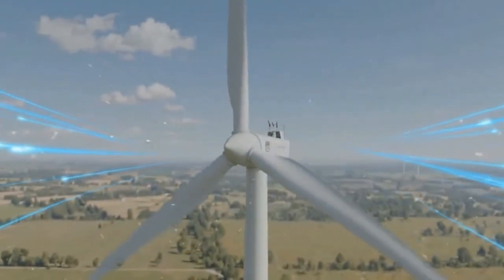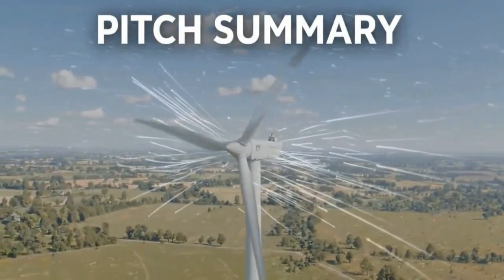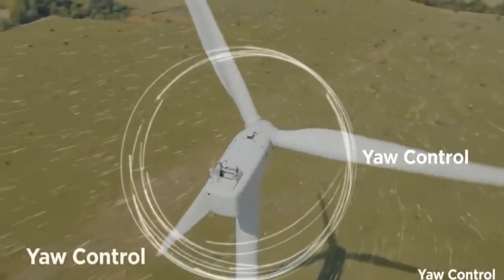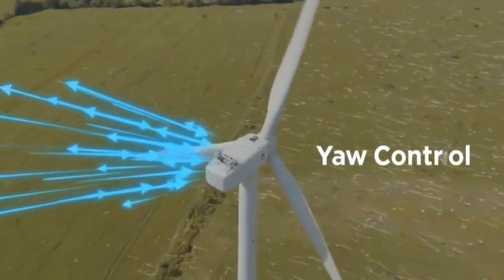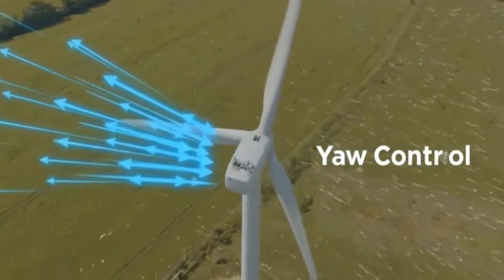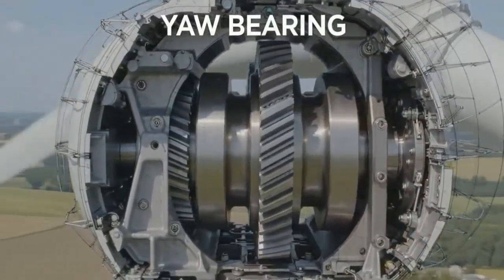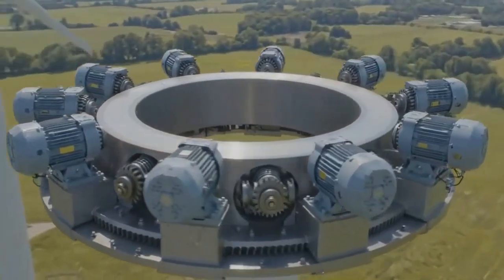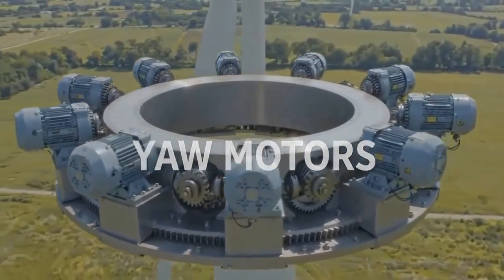In normal wind, the blade angle is set to create useful lift and keep the rotor turning efficiently. When wind becomes stronger, the blades rotate to reduce aerodynamic force and prevent the rotor from overspeeding. Comparing the two blade angles makes it clear. One captures energy, while the other lets more wind slip past.